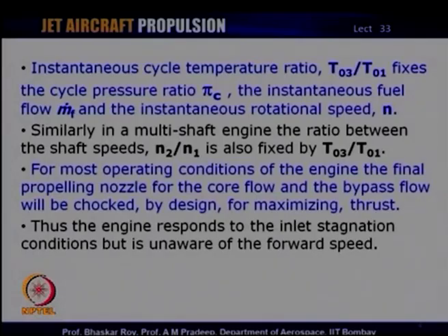Not that you get maximum thrust all the time, but for that operating condition you get maximum thrust. So, keeping the flow choked or maximizing the mass flow ensures that for that particular instantaneous operating condition you are getting the maximum thrust. So, the engine always responds to the inlet stagnation condition.